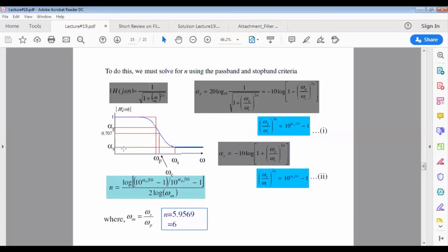In terms of the Bode plot, the low pass filter should look like this. We have a pass band, this is your pass band gain, the pass band region, and this is your stop band region. This is omega P and alpha P. This is a linear scale; in dB, this is supposed to be 0 dB, and this one should be equal to negative 1 dB. For alpha S, this is supposed to be equal to negative 30 dB, and omega S is 20 radian per second.